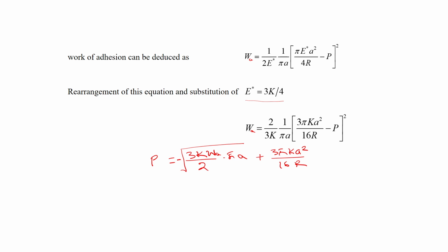Now, remember that this was the cylinder, in contact with another cylinder or a flat plate. If I see from the top, I will see the contact looking something like this, and let us say the length of the cylinder is 2L, and this quantity is 2a, like that. So, what I do is multiply this. P is the line load, the load per unit length over here, so we multiply P by 2L.